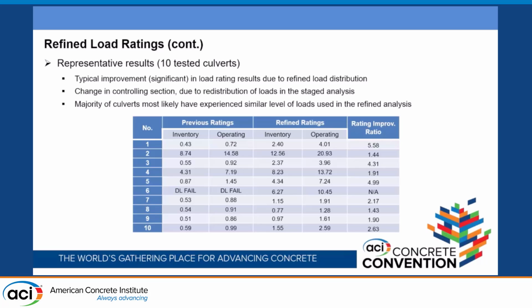The same result happened for the rest of the culverts, not only for the design vehicle, but also for the legal and emergency vehicles. And when it comes to legal and emergency vehicles, it's very likely that these culverts over the past 40, 50 years have experienced the same level of loading. So the results we get out of the refined rating, being above 1 for operating, line up better with the actual performance that we saw from them out in the field.